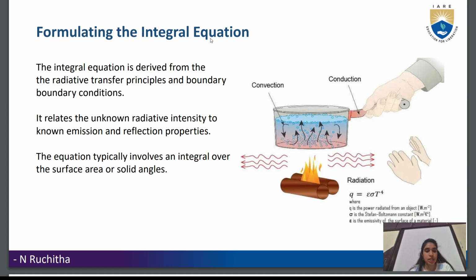Include effects such as incident radiation angle, spectral dependence, gray versus non-gray behavior, geometry via view factors or optical path lengths, and scattering phase functions for particulate media. The resulting equations typically involve unknowns such as surface radiosity or intensity distribution.